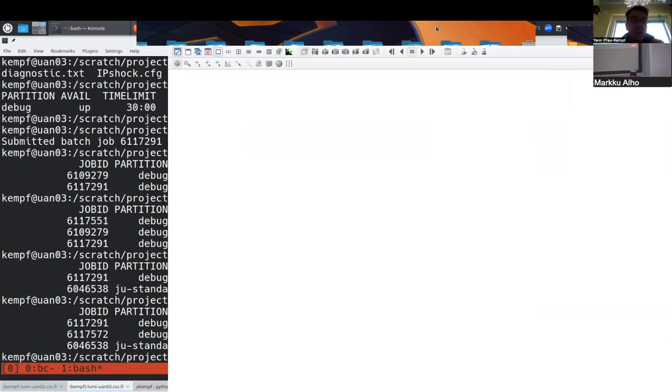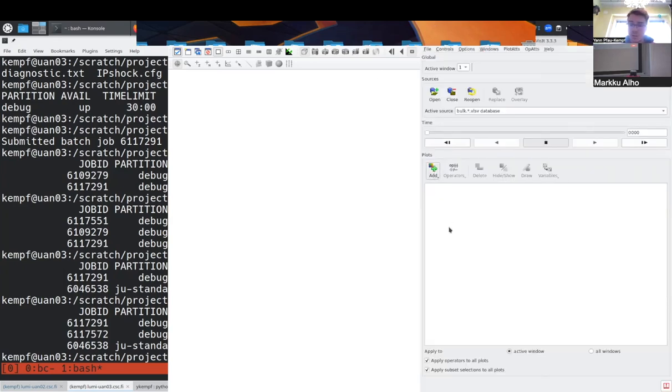For quick testing like we do today, I'm not too worried. If we only have a handful of points to sort of have a Maxwellian, that will be fine for demonstration purposes. Once you're running real simulations, you'll want to assess whether you have a lot of numerical diffusion. If you go too coarse in the number of points in velocity space, then because of numerical approximations and the mapping algorithm we use, it will tend to heat up pretty dramatically. You'll see that in your simulation. It's well possible we'll see that in this shock simulation as well. I can demonstrate what I mean in a few seconds.